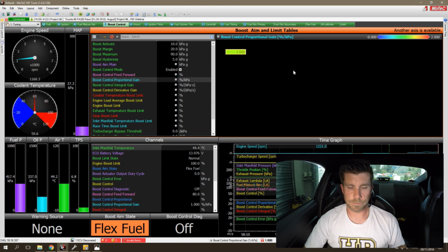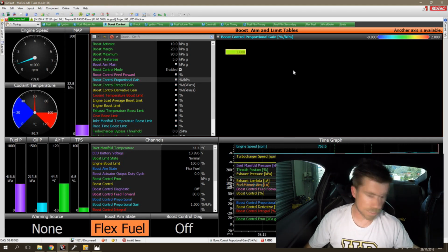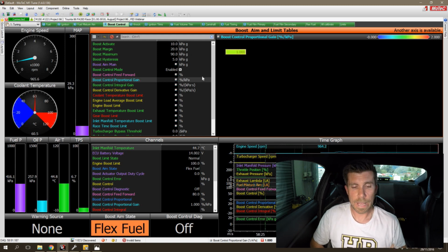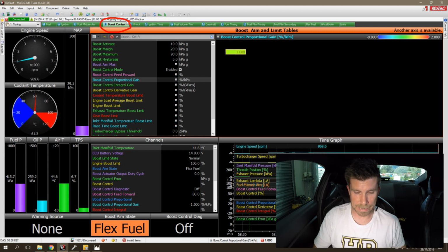Okay, let's have a look at some of these aspects in use now. So what I'm going to do is I'll just get our Toyota 86 started up on our dyno, and we'll jump into our laptop software here. So if Colin can just show the laptop, and I'll just get our fan running. Okay, so again, we're using proportional gain. We're using our boost control here as our example, and I'm on the boost control worksheet in our tuning workbook here on our Toyota 86 package.